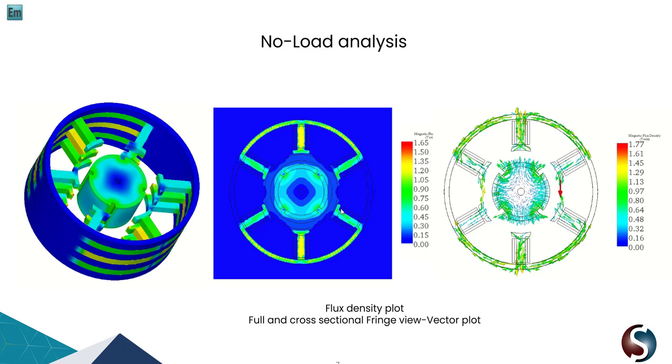And you may ask, so how does it all move? Well, we kind of fake it. We say, okay, let's assume a motion anyway using parametric analysis or the SolidWorks Motion, and we actually move the rotor without exciting the current. We just wanted to learn how the motion affects the torque as well as the fluxes and all of that.